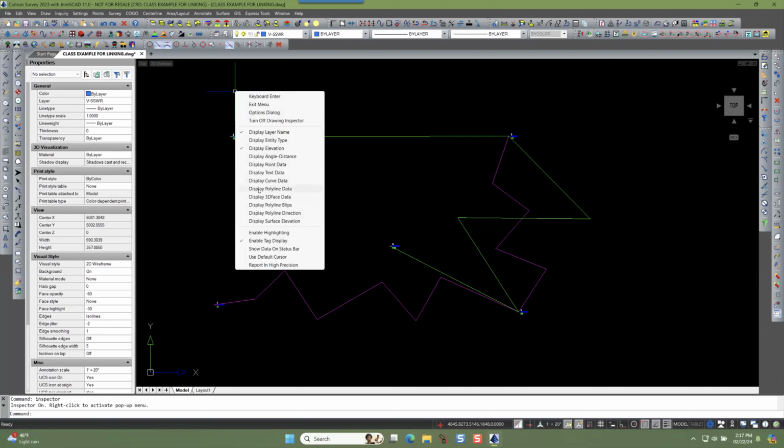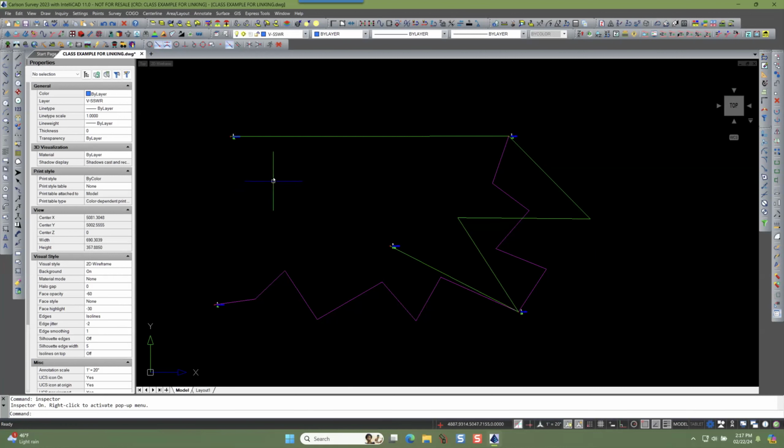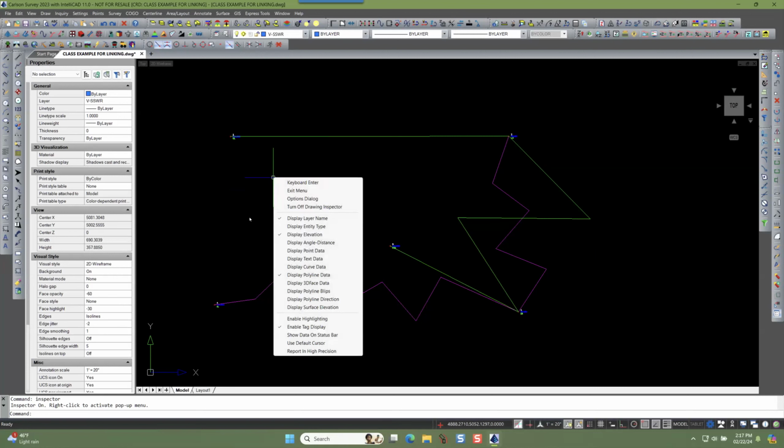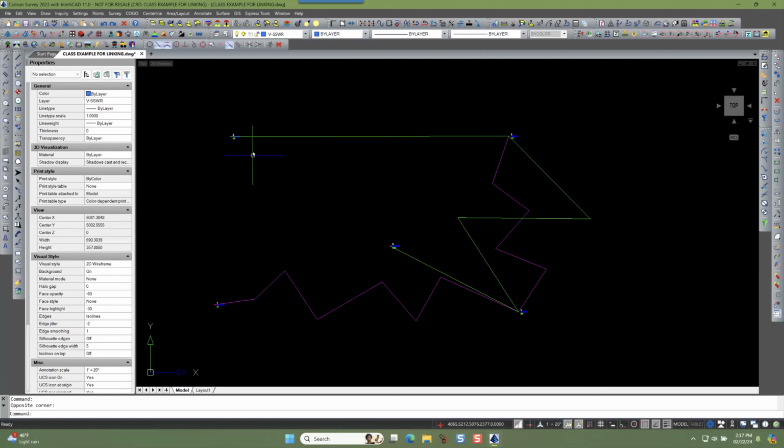So I'm going to go down to there and click it with the left mouse button. And now I see it's also on. So as I hover the mouse, right here, I see that is on a layer called 3D BKLN. It has an elevation of 101.411 at horizontal distance slope. You can read all that yourself. The total distance of the overall line, it is open, it's not closed, and it has a first point of point number 1, second point is point number 2 of that segment.